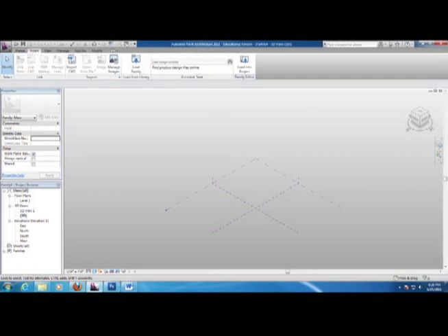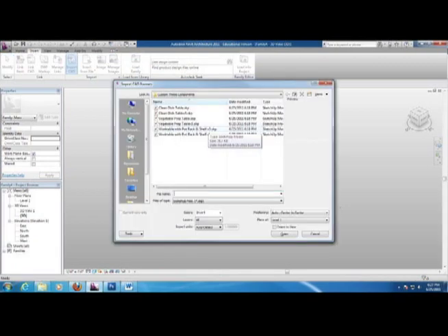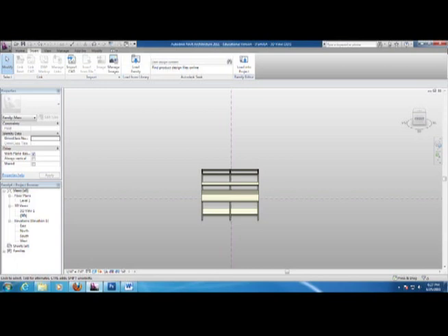At the Import CAD Formats menu, select the SketchUp Files.skp option from the Files of Type drop-down menu. Select your file and click Open. Your component should then be visible. Note that because it was not created in Revit, materials cannot be assigned to the mass. However, you can assign an assembly code to it if you wish.